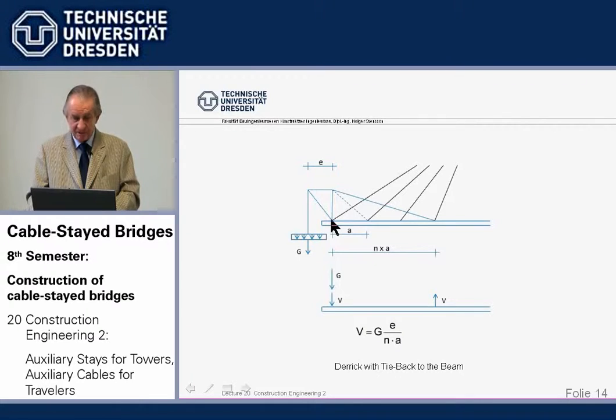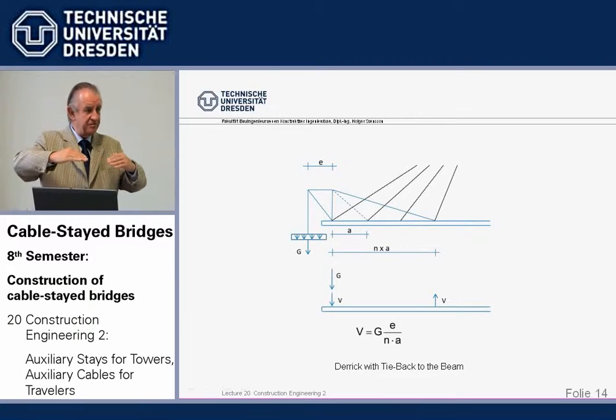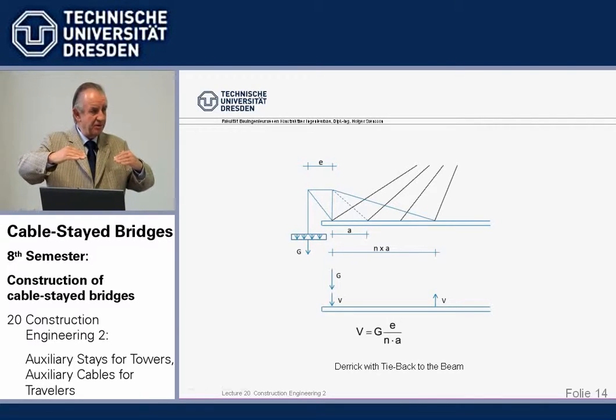But it's, in one word, such a beam is very, very sensitive against vertical loads at the tip. The same load, 3 cables back, doesn't do much. But here, we don't like it. So very often, the beam would be overloaded by this negative moment, tension at the top, from the weight of the new element plus derrick at the tip.